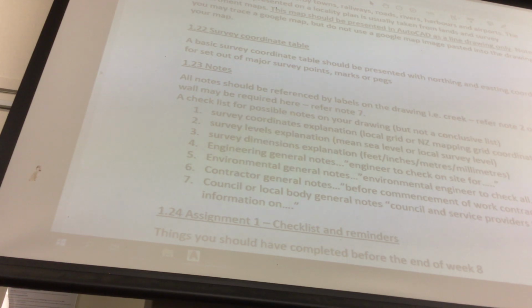This is a local survey. The coordinates are fictitious. However, often what surveyors do when they turn up somewhere and they don't have any start point is they find a manhole, because all manholes in Auckland have got GPS coordinates on them. You can relate it back, go into the council and get the GPS coordinates or whatever.